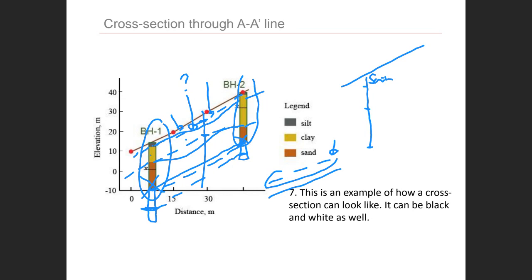Many students don't understand that, or maybe they just don't care. They just connect the end of the borehole and say this is the end of this sand layer, but it is not. We don't know. Maybe it is, but maybe not. We don't have enough information to make the statement. What we know for sure is that this is the end of the borehole log.